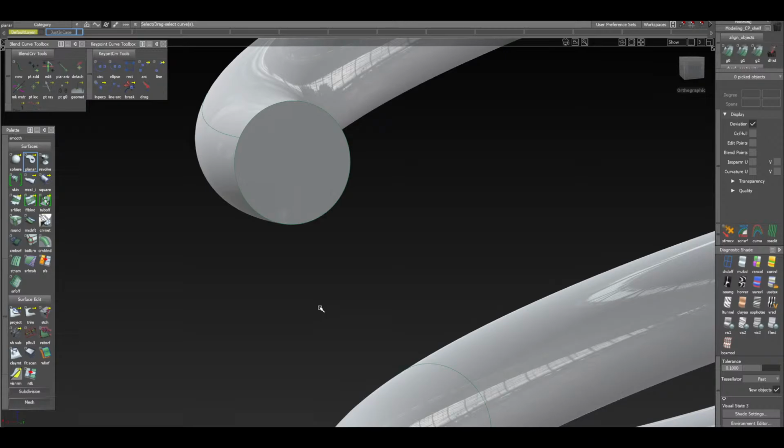I mean, it seems magical, but it's not really magical. In my past tutorial, I explained that 80 to 90% of the functions in Alias are based off of curves and surfaces, and really that's it. And the planar tool is no exception, because what it's doing is building a square surface.